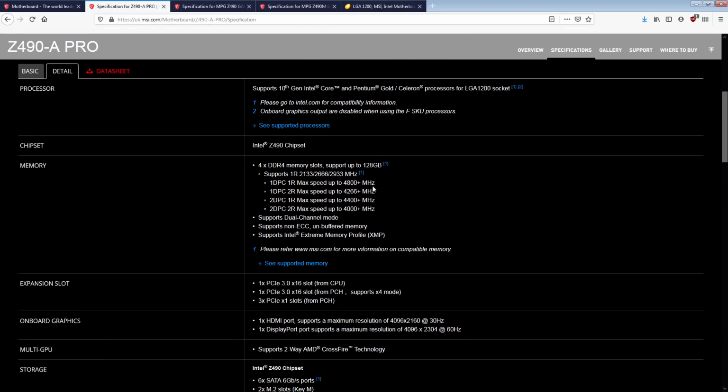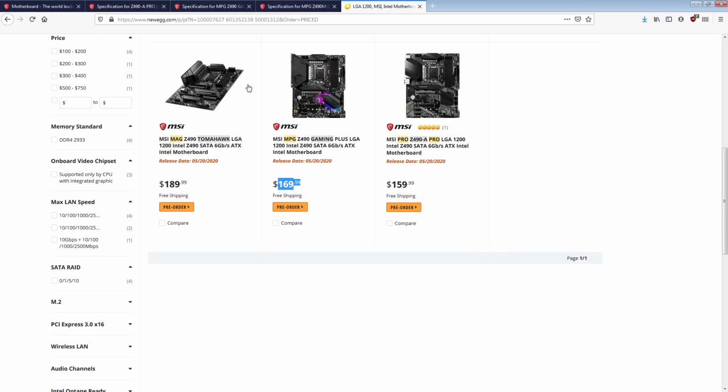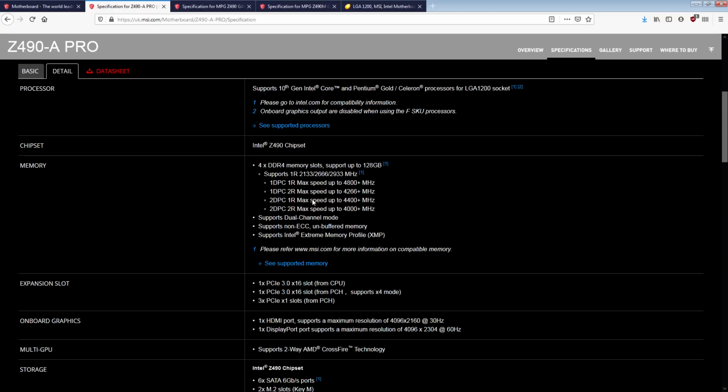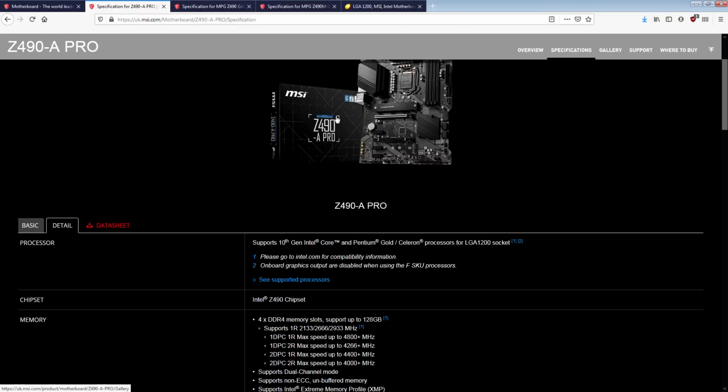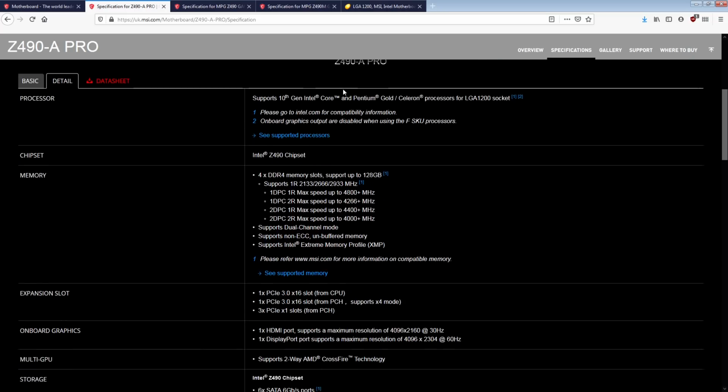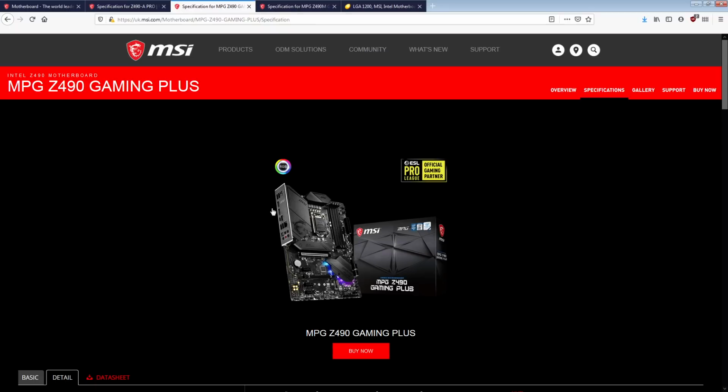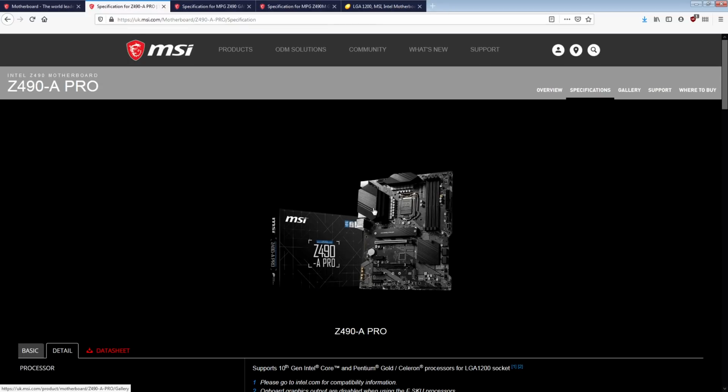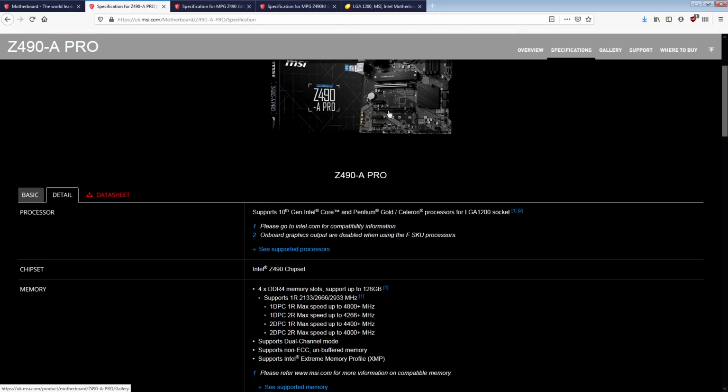Oh yeah, this still has the same 6-layer PCB. So that's really cool. I guess it makes sense. They just don't want to run different PCBs or different topologies at all. Actually, this is probably exactly the same PCB and they've just taken stuff off, or maybe shrunk the heat sinks. Heat sinks themselves are actually quite expensive, because they're not just bare aluminum blocks with a bunch of surface area. You've got all the inscriptions on them and the texturing and the anodization. I'm going to assume these are still extruded heat sinks for the main shape of the fin stack, but they ultimately end up cutting them funky, and that takes time and adds manufacturing cost.